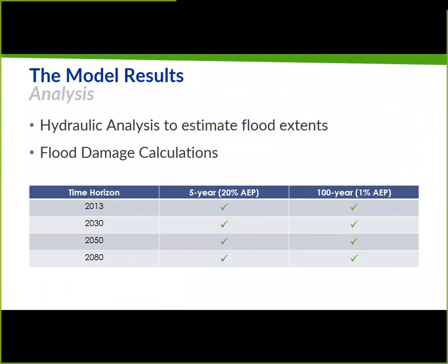Okay, so just to briefly recap, we talked about a few different time horizons. So 2013, that would be today's design standard, even though it's 2018. And then, as we mentioned before, the City of Surrey looked at expected rainfall intensities for 2030, 2050, and 2080. That's because 2080 represents the design life that you would hope to have based on an installation today.